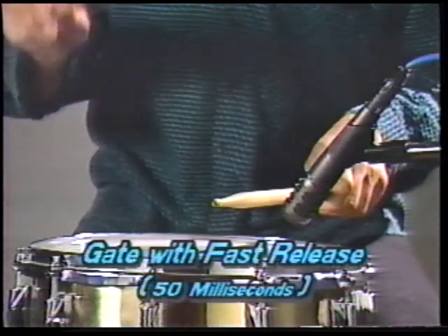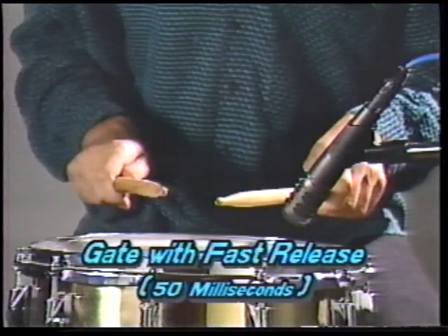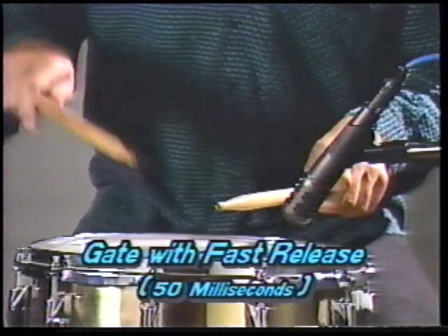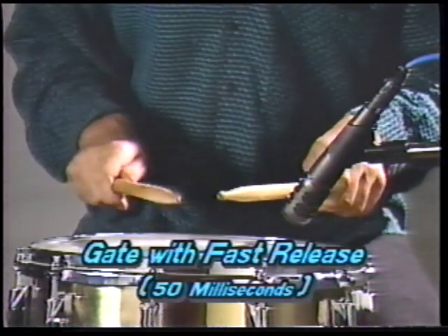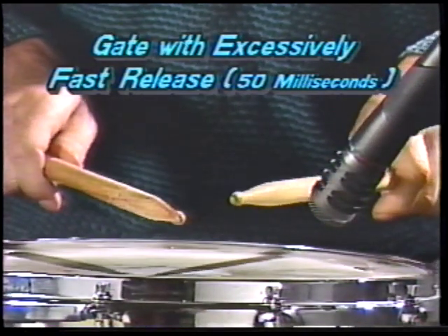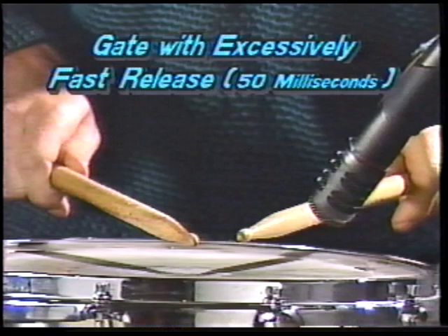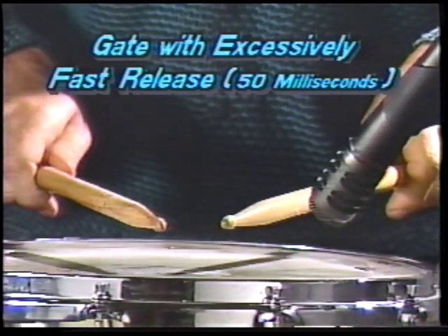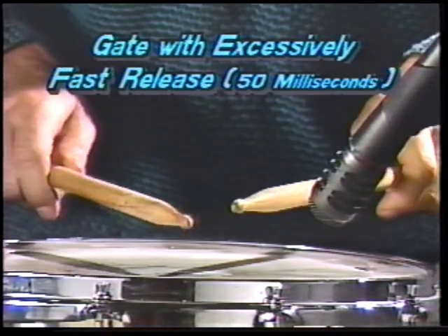The release time on a gate is how fast the amplifier will turn off after a loud signal has occurred. For instance, you would want a fairly fast release time if you were trying to gate out leakage on the snare mic. However, if the release time was extremely fast, the snare would have almost no rattle. In fact, the sound would almost resemble a timbale.